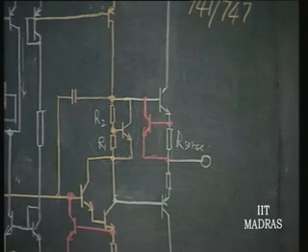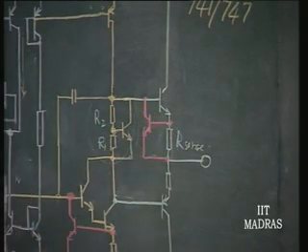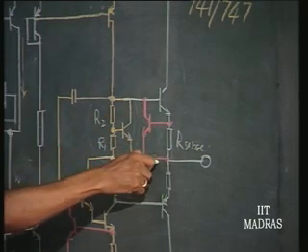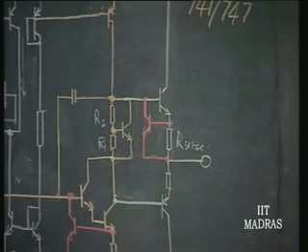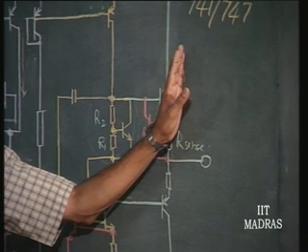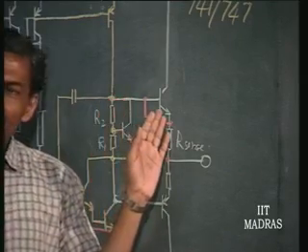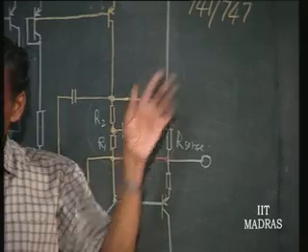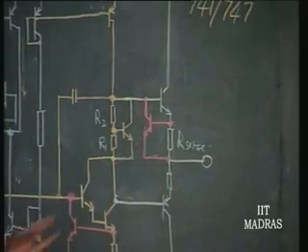The moment a current which is I into R sense develops a voltage V gamma, this transistor gets into the active region, okay, diverts the additional drive that otherwise would have increased the output current, resulting in the output transistor getting destroyed. Okay. So, this prevention of additional current drive which otherwise would have increased the output current is prevented by this transistor which is already put inside.